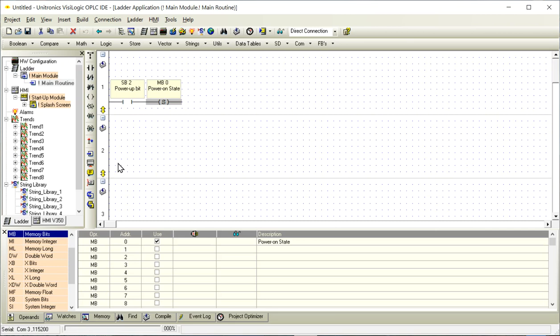Very quick introduction for people that didn't do PLCs before. The name of the game in this PLC is to get through this scan cycle as fast as it possibly can. And if you have a bunch of switches and indicators and lights, each scan cycle, it's looking at those things hundreds of times before they could change, so that it catches all the status that it wants to, to determine whether you hit a switch and things like that.